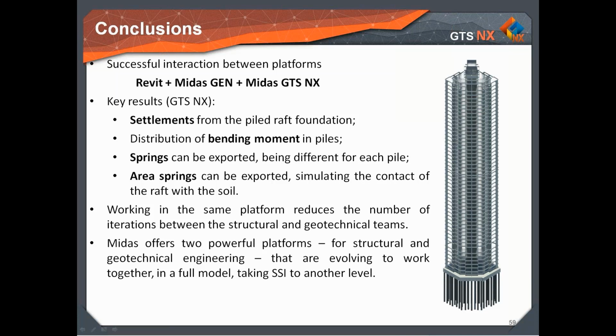Another thought is that having a quality soil investigation to retrieve reliable parameters from the soil is crucial, and also having an instrumented pile load test is crucial. So the result of our model all depends on the quality of this information. Thank you.